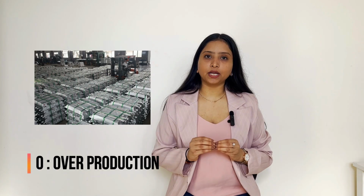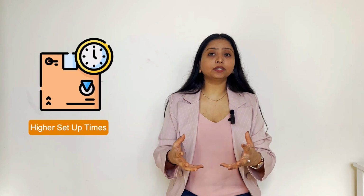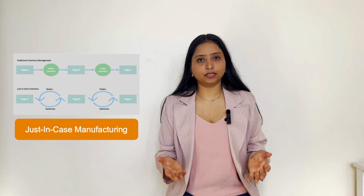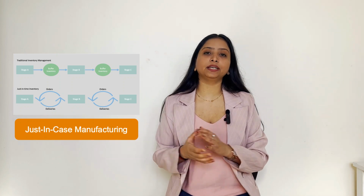Number two is overproduction, producing more or sooner than what is needed. Now, how do you identify overproduction? Let's see, you have higher setup times. You're changing the product design when the first design is already in the process. Or you're doing what is called just in case manufacturing. The first process is giving out components when the next process is not ready to take it in.